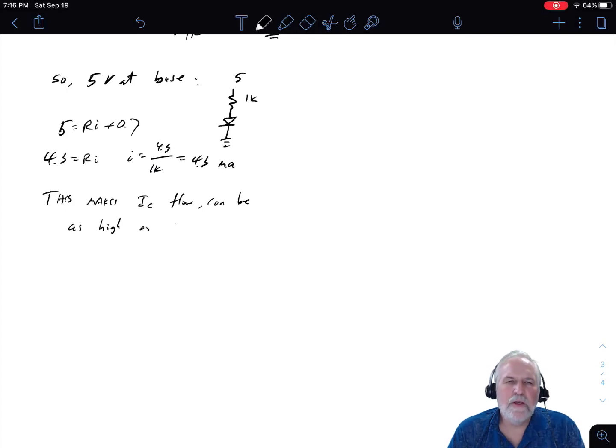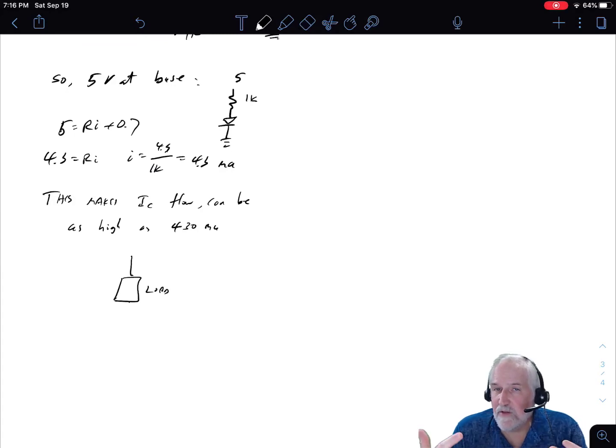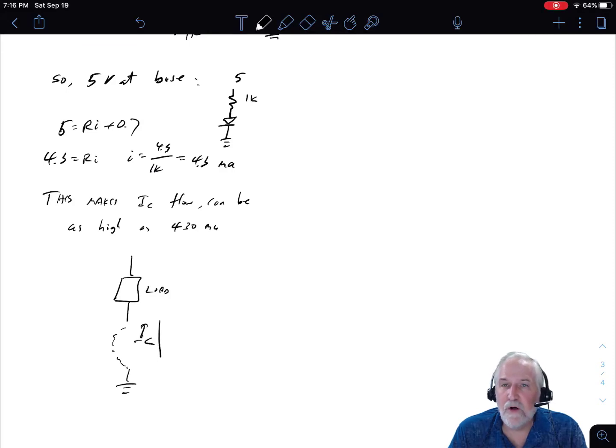So what we're showing here is what I mentioned earlier, that when using the transistor as a switch, if the voltage drop across the load approaches VCC, in other words, if you pump more and more current through it, it generally will have a higher and higher voltage drop, right? There's almost always some resistance in that load. Then the voltage drop across the transistor gets smaller and smaller because most of it's being taken up by the load, and there's a limiting value of V_CE, the collector to emitter voltage, and it's 2/10, 3/10 of a volt.